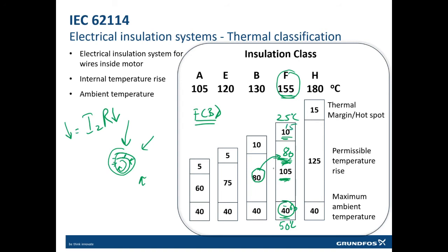So I give this 60 and I make this 15. So now my motor can go up to 60 degrees with even insulation class F. How? By improving the internal temperature rise. Now my internal temperature rise is not going to 105. Now it is going to 80 degrees. That's the meaning of insulation class F to B, or something which is written like this.